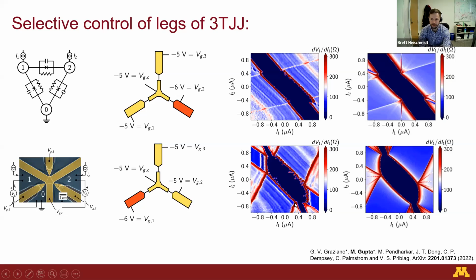Yeah, well, that's what I'm curious about. What kind of dirty secrets do you have that you get these two things to match? So the one important thing is that the values of the resistances and the critical currents that you measure in experiment don't always translate to the simulation. You always have to change them, because the values that you measure experimentally are hindered by heating effects and hysteresis, and the capacitance is added to model that. So you do have to do a little bit of tuning, but there is not really a set pattern. We have to do hit and trial. Right. Got it. Thanks.